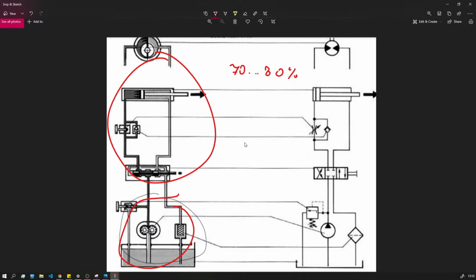We will have the lab lessons, and in the lab I can show you an example using a short hose: about 1 bar of pressure loss for 1 meter of hose in our system. So if we have a 2-meter hose, it will have 2 bars of pressure drop over that hose. The pressure drop means that we are losing energy just by moving the liquid through that hose. Not ideal. Anyways,